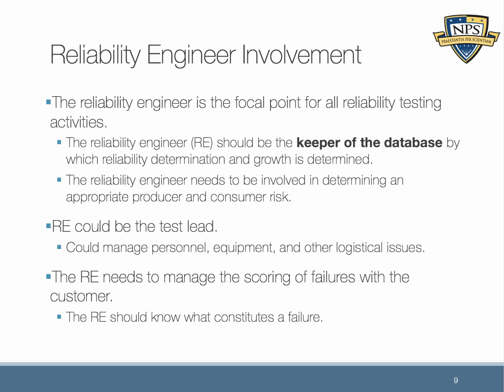And then the other thing that the reliability engineer would be involved with, at a high level, is determining the scoring for the failure. One way to think about this is what really constitutes a failure. It's interesting because I've seen in practice that this is very poorly understood. We go into a test and it seems very obvious what a failure means. It's usually, okay, a dead unit is certainly a failure. But if you don't think about the exact test being run and what some of the different outcomes might be, it may be uncertain what a failure is.